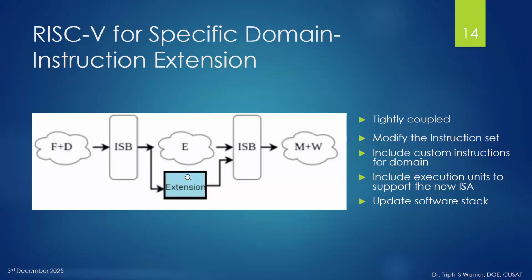When you add a new instruction here, you will have to update the software stack. That means when you want to run a program which uses this extension, you have to have a compiler which identifies a sequence of C program snippet which can be mapped to that extension.